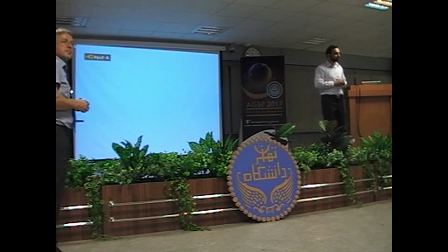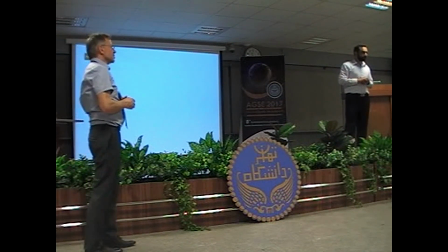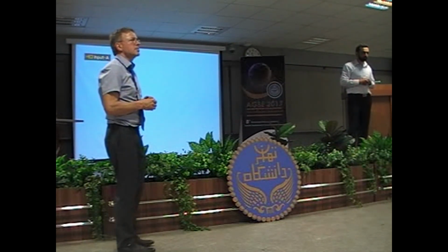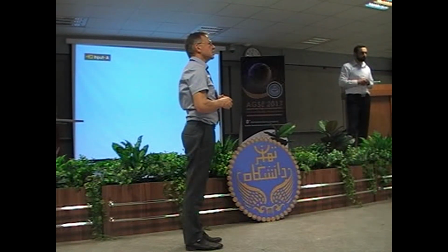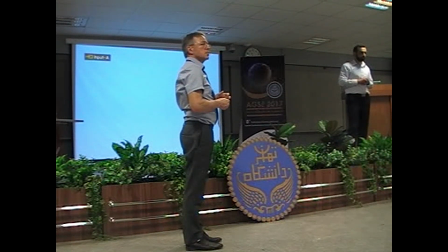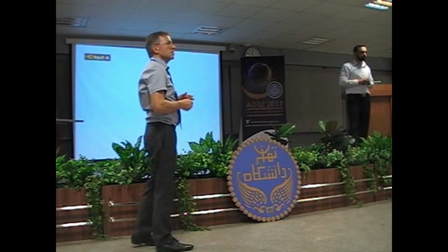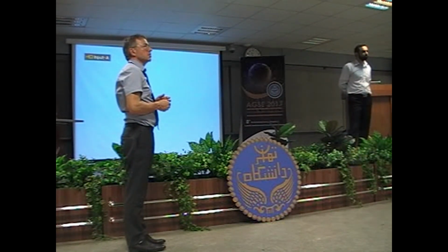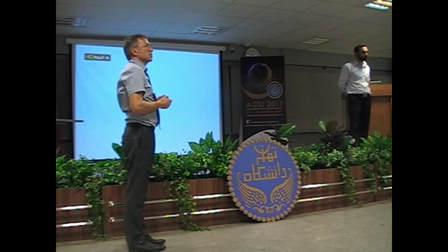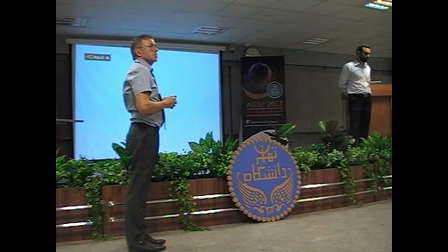I have a question about your formula: interferogram is equal to flat earth phase plus digital elevation model plus deformation plus atmospheric. You mentioned that when you want to derive the displacement information, you need to subtract the digital elevation model.